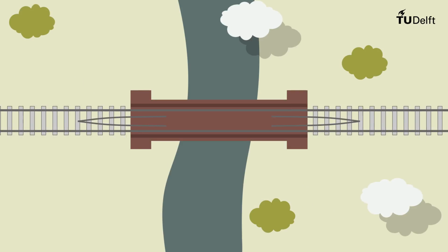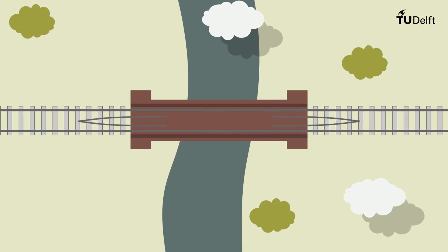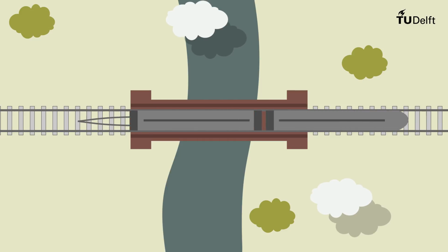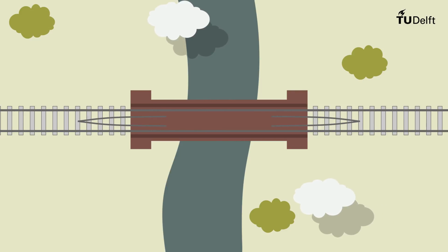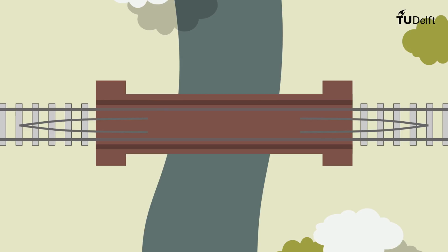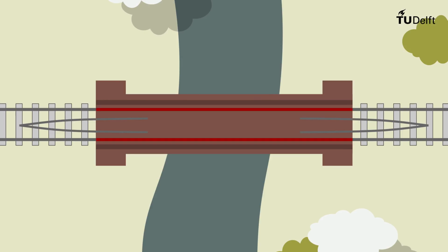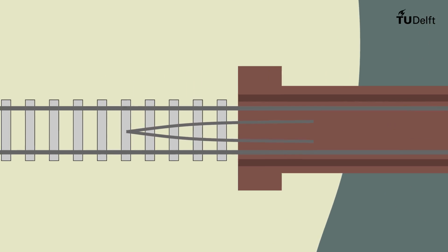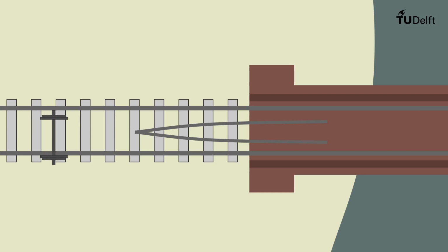Railway lines may also cross over or under roads and rivers using bridges, aqueducts, or tunnels. In order to reduce the weight of the track to be carried by the bridge, the rails are usually directly fastened to the bridge deck. Guardrails are placed along areas of restricted clearance. These rails keep the wheels of the train in alignment in case of derailment. This way, damage to the structure is minimized.